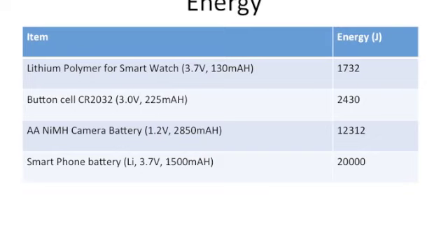The energy is voltage times current times time. So that tells me that if I have a certain operation which takes some amount of energy, then for a given amount of battery there are only so many operations I can do. So if I want to maximize the lifetime of a battery, what I need to do is reduce the energy per operation.